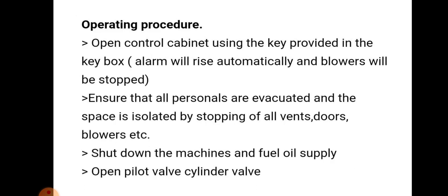Operating procedure. Open the control cabinet using the key provided in the key box. The alarm will rise automatically and the blower will be stopped. Ensure that all personnel are evacuated and the space is isolated by stopping all vents, doors, blower, etc. Shut down the machines and fuel supply. Open the pilot valve and cylinder valve.